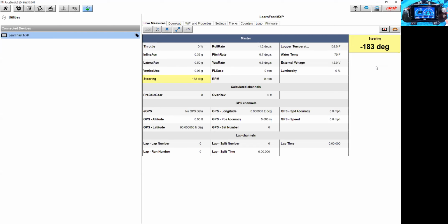As Robbie just mentioned in the chat box as well, the one that we just did is a 10-turn, or 3,600 degrees for that 0 to 5. So the resolution, this is a fairly inexpensive sensor that we just used. But as you can see by the numbers, they float around a little bit because that resolution's fairly high. But you're certainly getting data that is very much usable for your use typically.